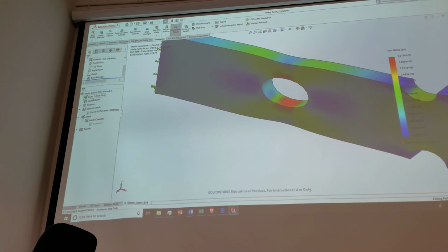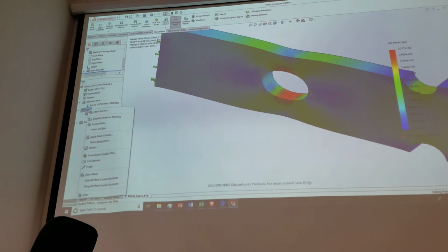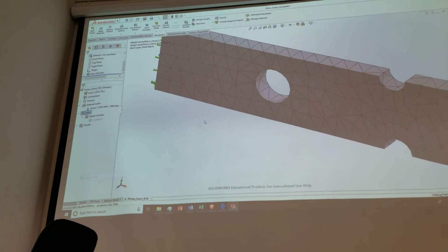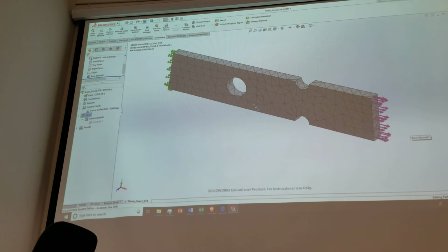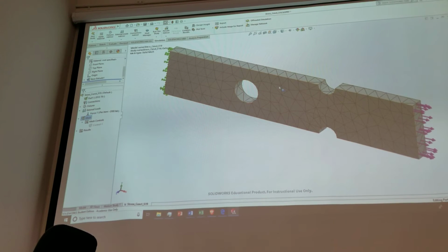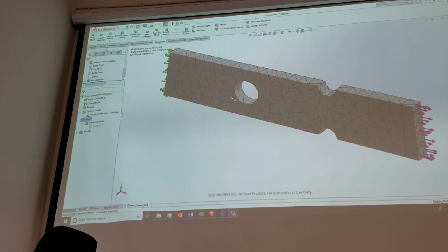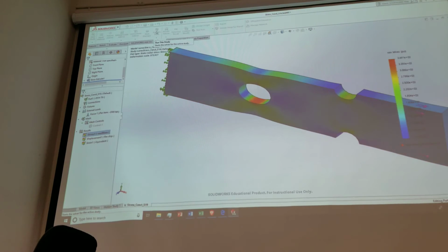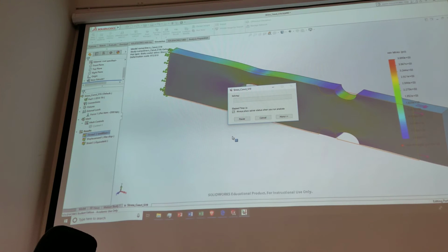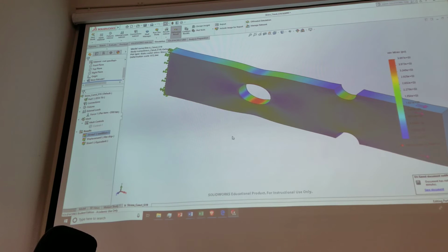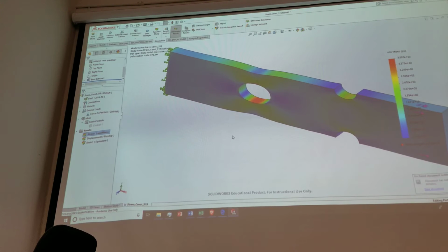So if we look at the mesh for this part, I'll show you the mesh to start with. This is what the default mesher gave me, one element thick, kind of going around here. And if I run it, it's going to run multiple times, and you can watch it refine the areas in there. So here's the 4th time through, and now it gave up after 4 times. This is the H-adaptive.